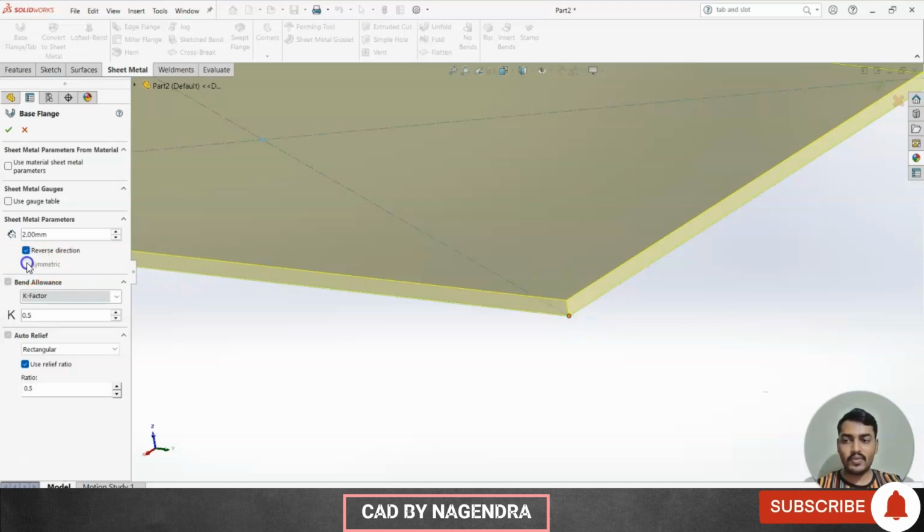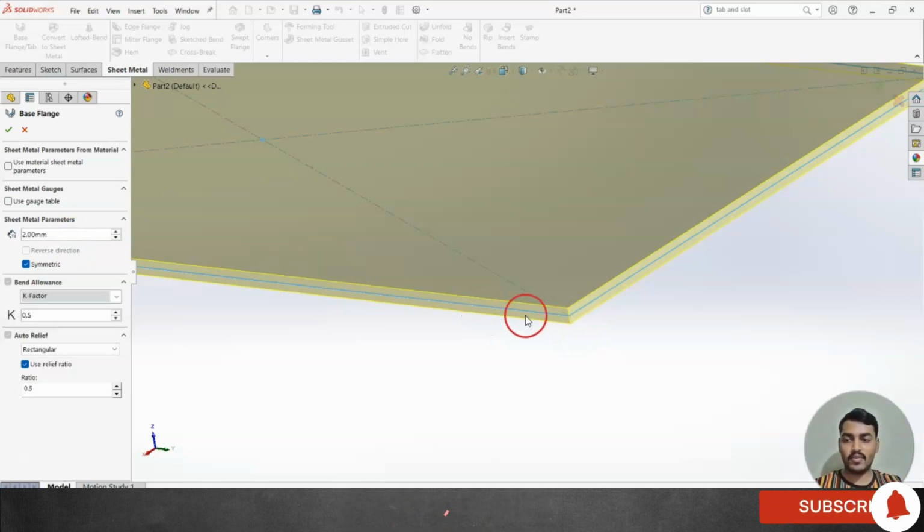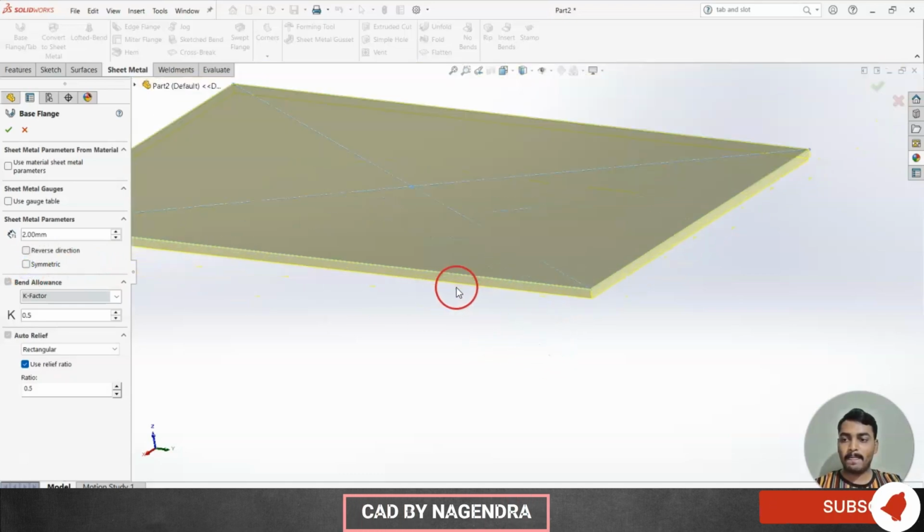Or else we can use symmetric also. Symmetric in the sense the sketch will be exactly in the center. So total 2 mm, right? 1 mm thickness will be adding in the upside direction, 1 mm will be adding in the downside direction. So I'll keep it normal like this. Then bend allowance will be there. In the basic class we have discussed what is meant by bend allowance, then what is meant by K factor. So this K factor value should always be between 0.25 to 0.5, that is a standard size.